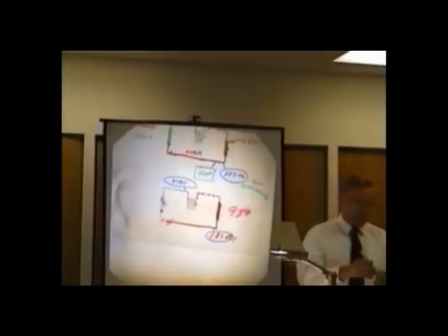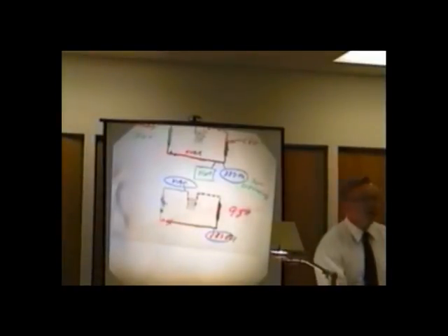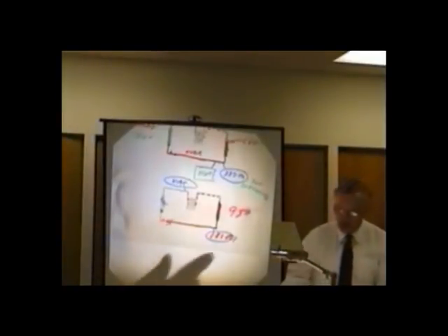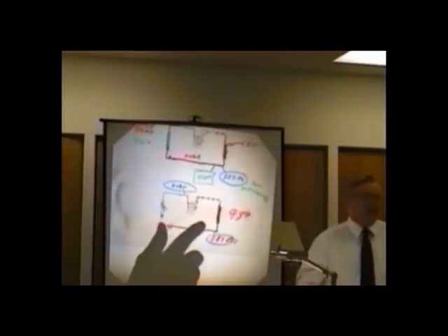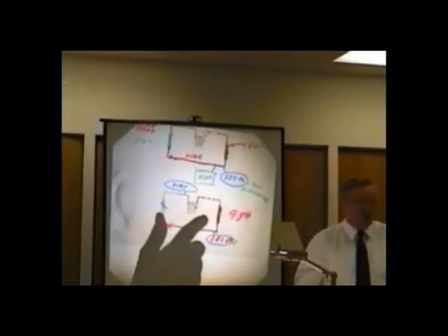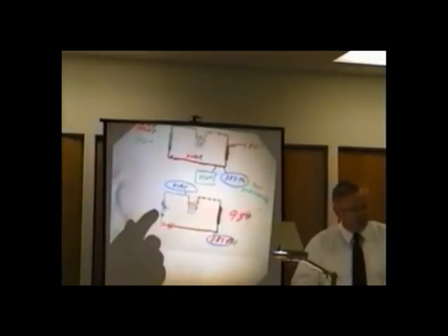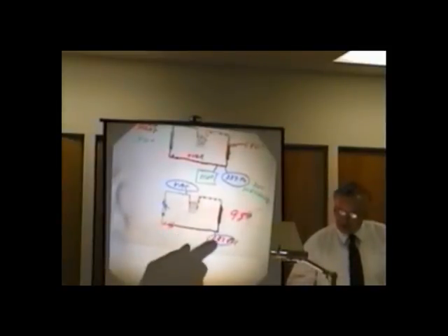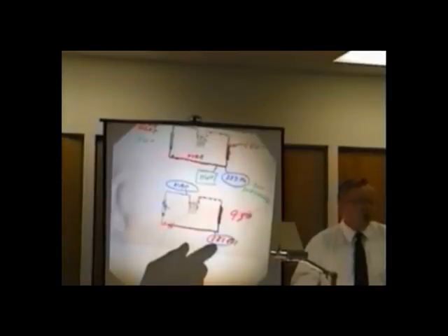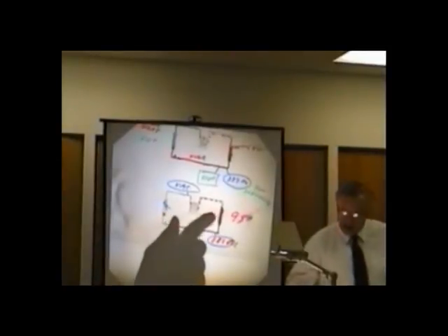Sorry, I get excited. I get so excited about this stuff. This is so good because once you learn this, you can do anything in refrigeration. Gentlemen, this is like a tank of gas sitting on a table. When you get this system delivered, it is completely charged, with a charge enough for 25 feet of standard line set. We said it's 100% restricted, and the technician puts his gauge on here and says, oh, it's low. But the condenser is big enough to hold the entire charge and then some. So where's it going to go?